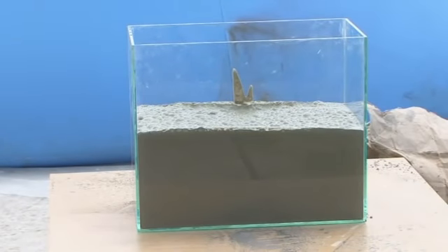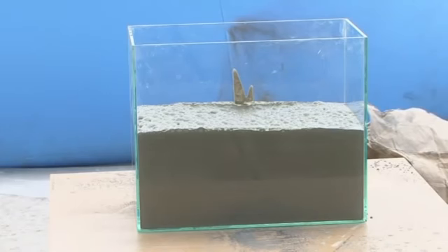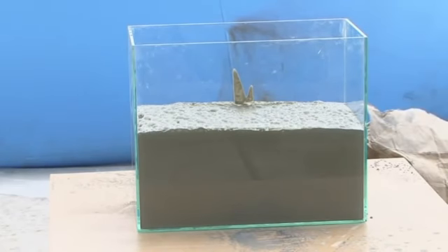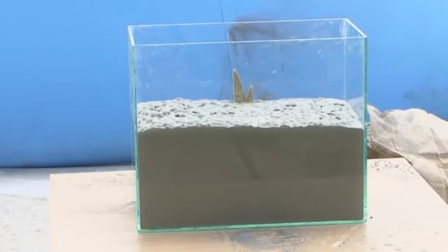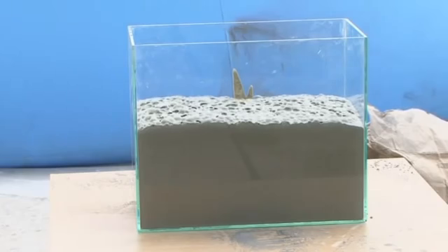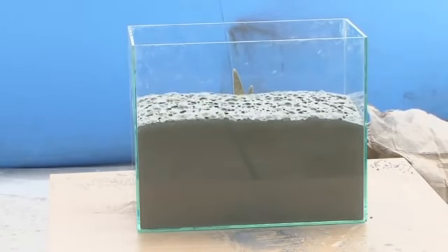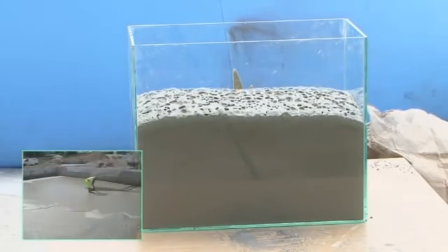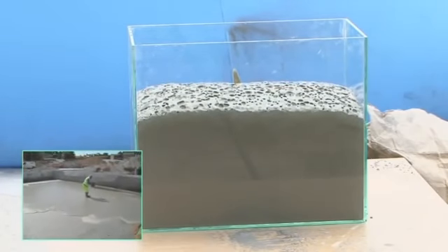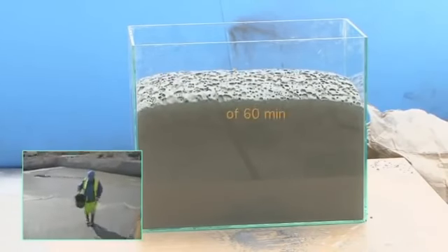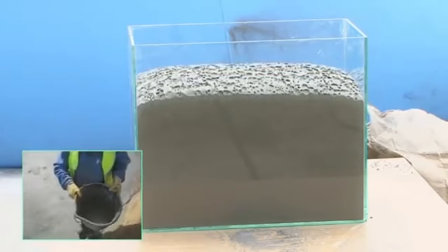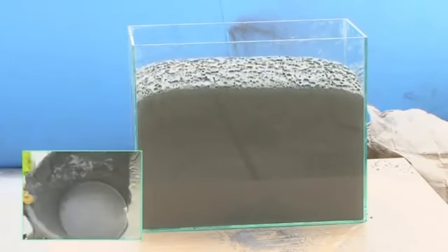Mixing of the components with water produces aerated cellular concrete with density varying from 250 to 1,400 kilograms per cubic meter. The uniqueness of the CFC dry mixture technology is that there is no need for a concentrated foam agent with water that would produce foam from compressed air with the special equipment necessary for the purpose. To prepare cellular concrete from the CFC dry mixture can be used practically any existing on the construction market concrete mixers, mortar mixers or dry mix mixers.